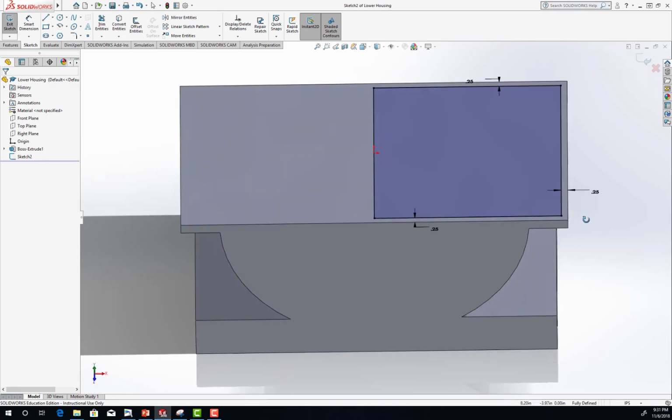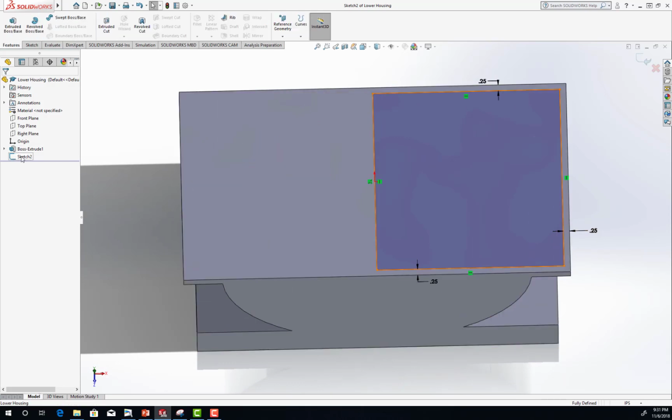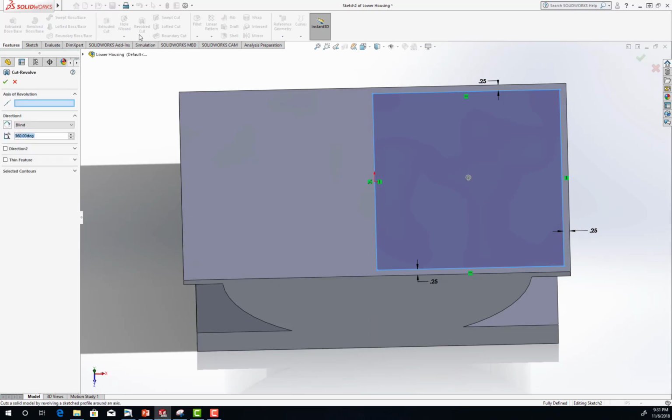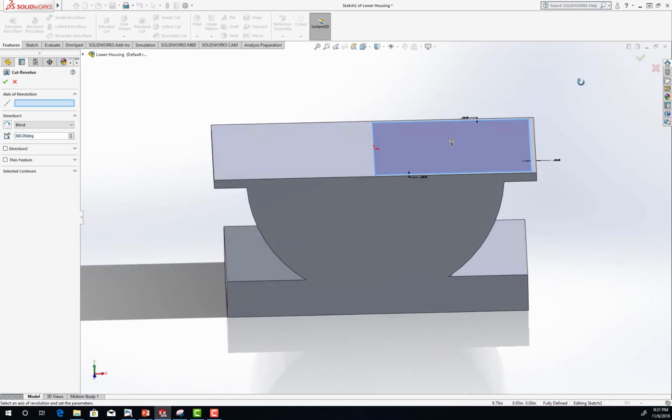Now we're going to do the Revolve Cut. So let's go back to features and select the sketch tool first. Then do the Revolve the Cut. And this is the direction. It's going up, probably not right. So we select it, make it go down. So direction. So select this, go down. Then instead of a 360, let's make it a 180. So only get half cut.